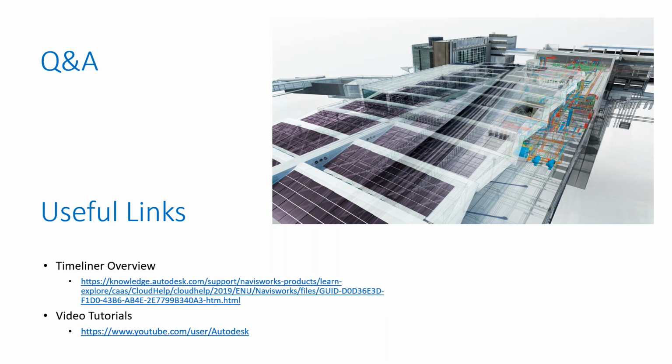Okay, so a question came in from Mohammed. How do you control the rendering of the video? It looks better than what we did earlier. Yeah, so the video that you see now, which my colleague has made, also uses the Autodesk rendering engine. I don't know if you remember, at some point we showed how you can render using the viewport, which is just a normal geometrical render with no textures, no shadows, no lighting, versus the Autodesk one.